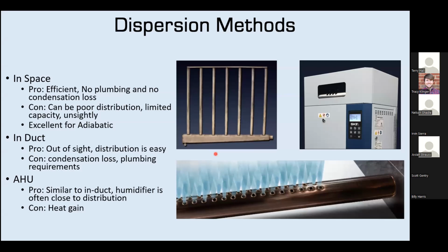For dispersion, one of the best, easiest methods is in-space, so that's on the right. Instead of ducted dispersion, this is the most efficient. The only problem is you have a humidifier then in your room or in your laboratory.